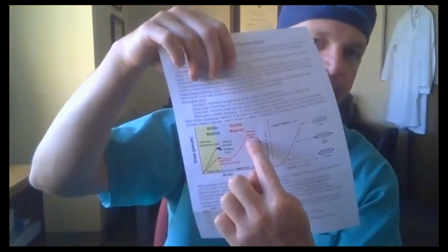And you can bend it once and you can plastically deform it, so you reach its yield limit, but you haven't reached its ultimate tensile strength so it doesn't break, right? So you haven't fractured it, based on what we were talking about on this piece of paper. You didn't break it up here. But if you do that again and you do that again, the same amount of force, you're not going past the yield or past the ultimate tensile strength. You do that same little micro motion over and over and over again. You do that 20 times or 50 times with a coat hanger, it's going to eventually break, right?